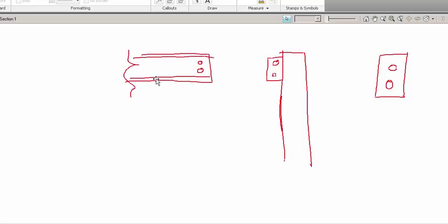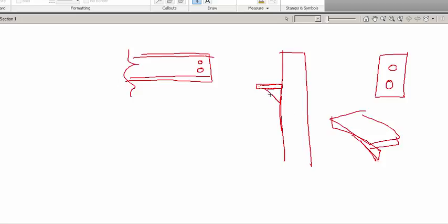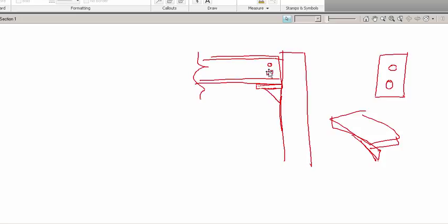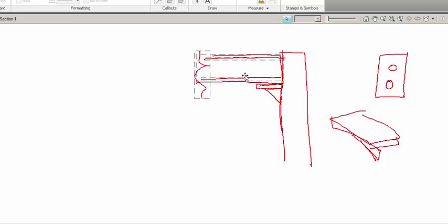Another example is what they'll do is they'll actually take plate, see if I can delete this off and leave the other piece, take plate, and we'll do a gusset plate, where we'll take a piece of plate, weld it to the side, and maybe add a triangular piece of plate down below. It looks kind of like this. Here's the top plate, and there's the triangular plate down below. We'll weld it again in the shop, and then we have to do field install. We're going to set it right here. I shouldn't have holes on this because we're not using holes this time. I'll get out to the field, and then I'm going to place it on top of the actual plate, let it sit there, and then I can apply more welds as needed. So plates are used for a variety of connections.